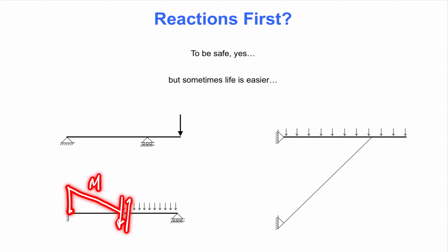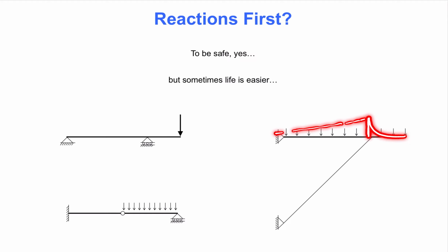The beam in the structure on the right-hand side is carried by a pinned support on the left-hand side and the inclined truss member near the right-hand side. That means we find the bending moment diagram for this beam in a manner similar to what we did for the first structure considered on this slide. The bending moment diagram for the cantilever is known from the previous slide.